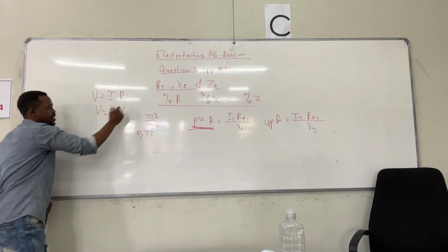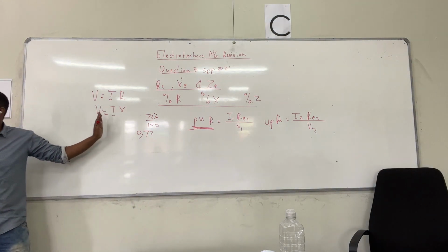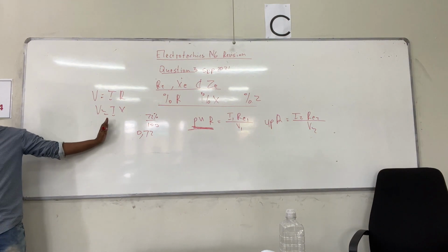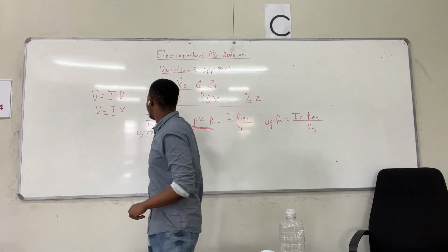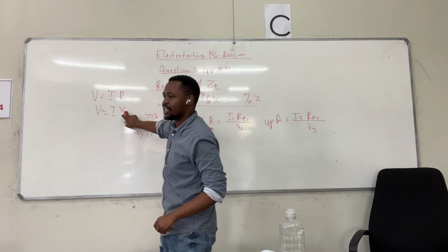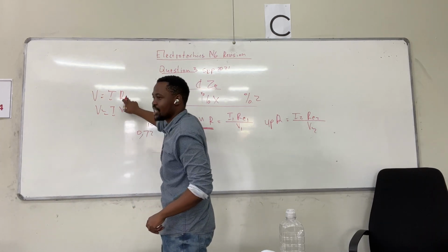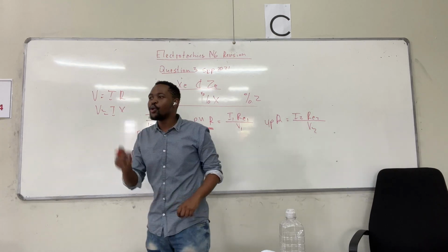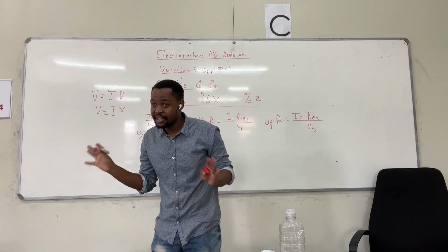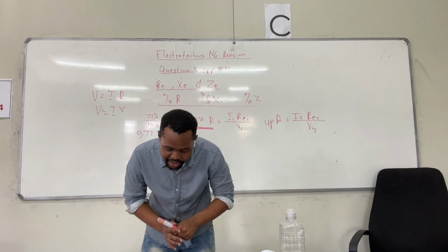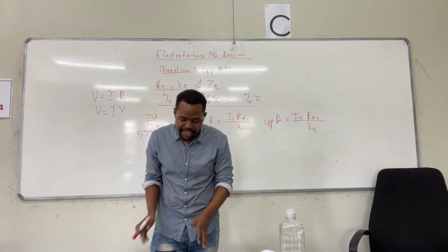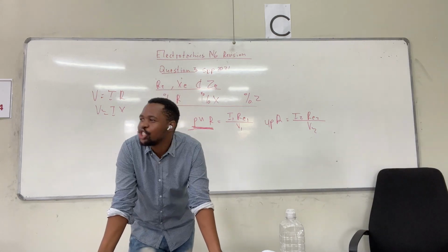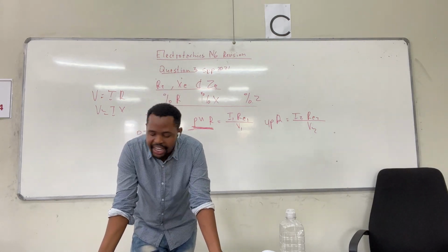But when resistance and reactance are given in percentage or per unit form, we don't need to know the current. Likewise, if we are given percentage or per unit impedance, we can calculate the voltage drop without a current value.